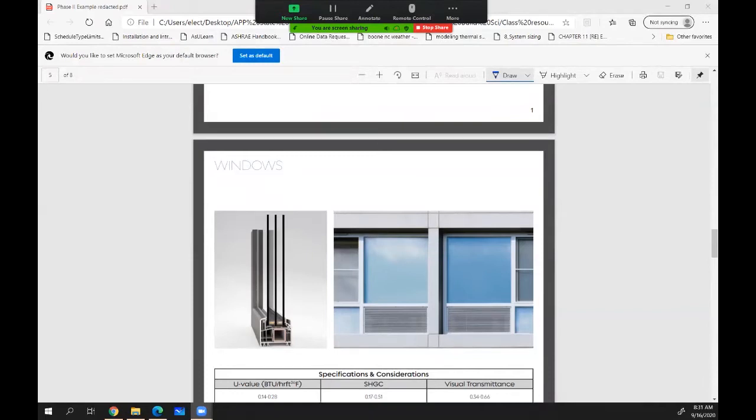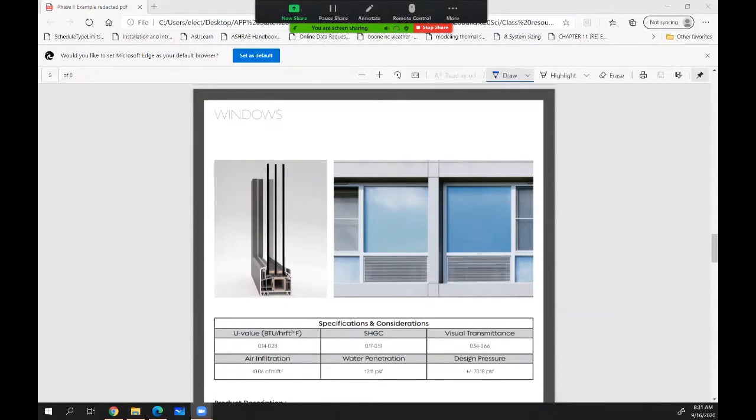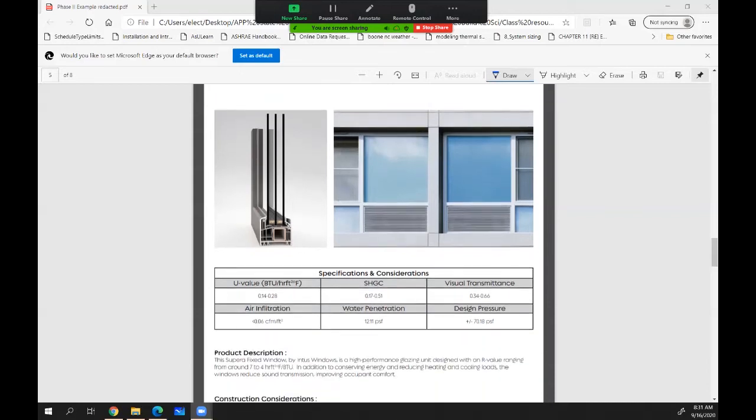Again, I want you to specify a climate zone, look at the code for that climate, and look at insulatory values, stuff like that. Maybe look at perm ratings for your water control layer. We'll talk about that more when we get into water control, or for your vapor control, rather. Take into account how much humidity is in the environment where you're designing for.